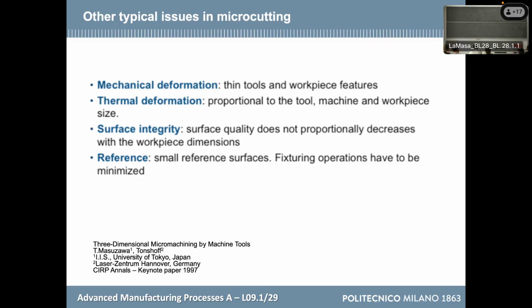You know for sure the theory. Maybe you haven't applied it to this case, but you know why. You just have to find it. It is a bending action, right? When you bend, you have to achieve the ultimate tensile strength of the material. But if you remember those formulas, you need the distance from the neutral axis, right? But what happens if you have a fine layer of material? If the layer is too fine, you never achieve the ultimate tensile strength.